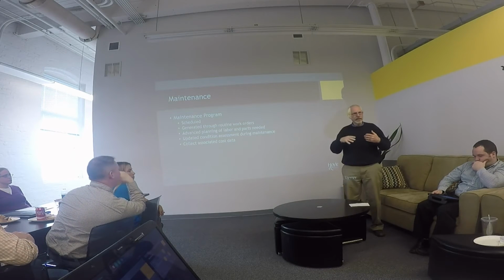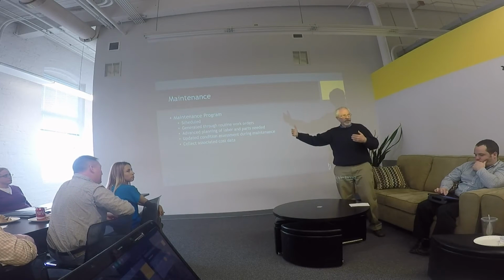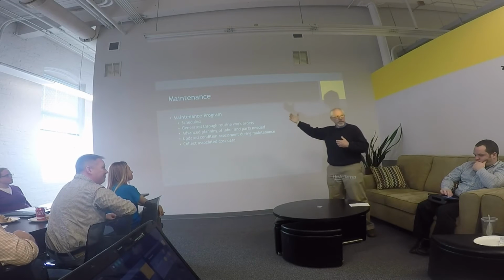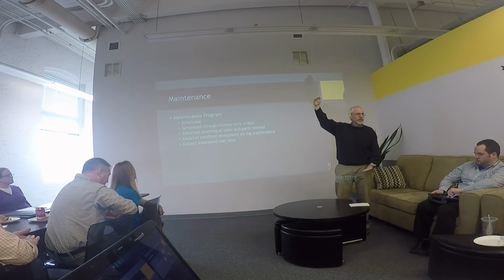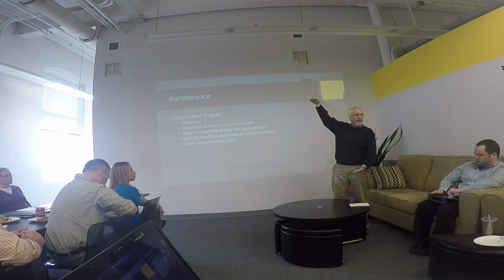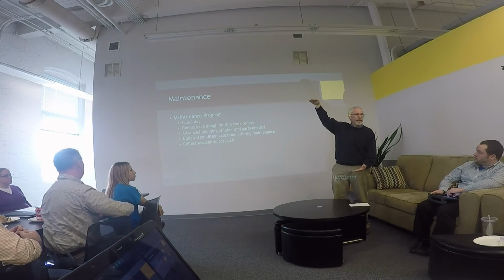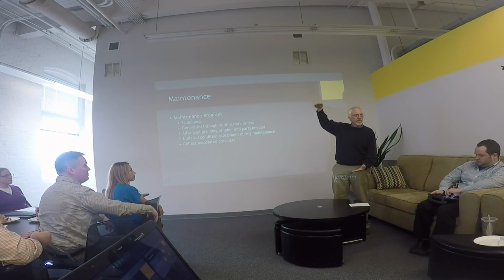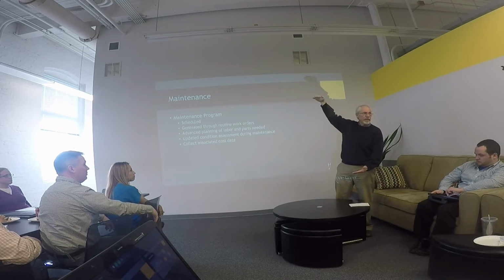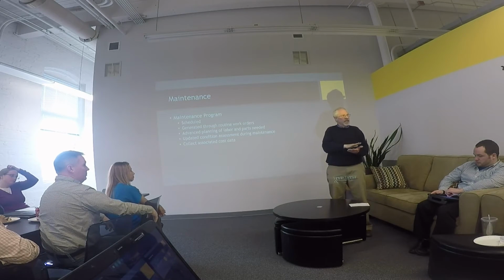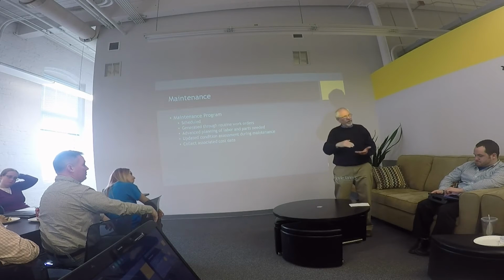And we're going to be doing training Thursday in Portsmouth. Actually, it's probably a couple weeks out, we'll be doing condition assessment. Do we want it as a deduct condition? So you start off at 100, and every time you find a defect, you're deducting from 100. It's like the PCI. If you have brand new pavement, you start off at 100 and then you go down. Now, that's one way of doing condition assessment.